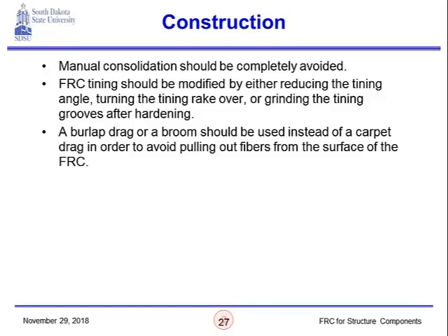A burlap drag or a broom should be used instead of a carpet drag in order to avoid pulling of fibers from the surface. This is the same, something that was advised by other DOTs that had experience with this specific issue, where they had the fibers being pulled once they do a carpet drag on the pavement.